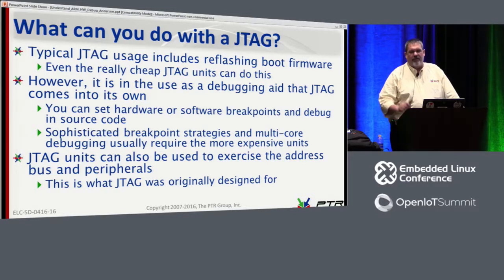So when you're setting up the chip selects, turning off the data cache, invalidating the instruction cache, disabling the MMU, turning off the interrupt controllers, setting up a C calling stack, all that stuff is done in assembly language. So with a JTAG, we can debug that. Without a JTAG, yeah, you're really kind of on your own on that one. It's going to be really difficult.